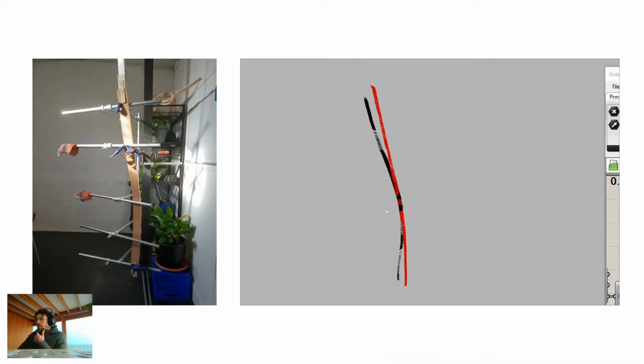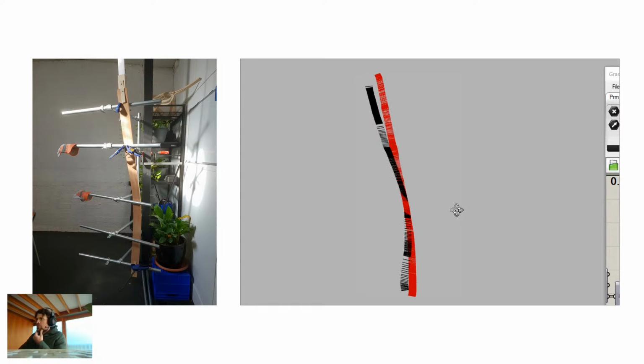Now, one of the first things that we had to overcome, and we'll continue discussing these sorts of ideas throughout the workshop, is how you manage the springback of the timber. And again, this is why I think steam bending hasn't been overly commonly used as a fabrication technique. On the left, you see a piece of timber on a jig that Sean and I designed that was set up following a hologram so that you could bend a piece of timber over it into a precise shape.